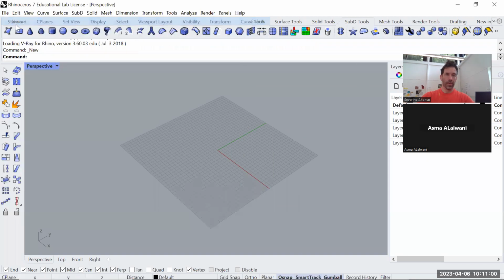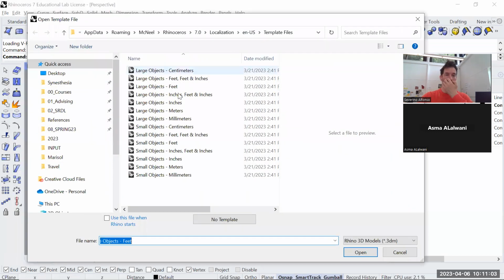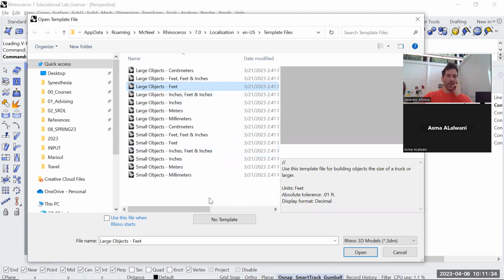When you start Rhino, it's going to give you a set of options like this. This is the unit setting, depending on whether it's a large file or a small file. Normally you will click what you need. Is it a large object or a small object? The only thing that could be doubtful is that large is basically building up, so from buildings to cities, and small is basically building down, maybe doors and furniture and knobs and details. So I think we're in the large object option. It wouldn't matter too much, so I wouldn't worry, but the option is something that we definitely need to set.